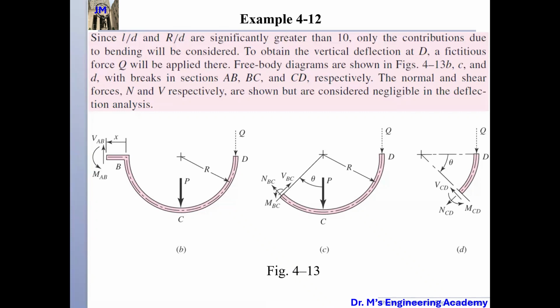You can see for M_CD here, I only have one term, and this guy Q equals 0. That means delta 3 will be equal to 0, because M_CD equals 0 if Q equals 0. You guys agree? Just follow this procedure, and finally this equals 0. Then finally, the delta equals delta 1 plus delta 2 plus delta 3, and you can calculate it.